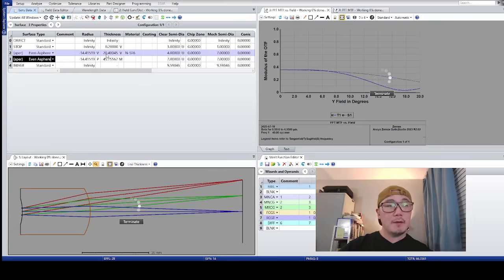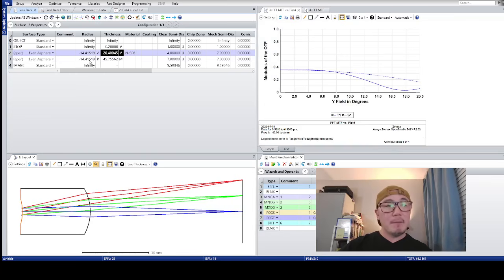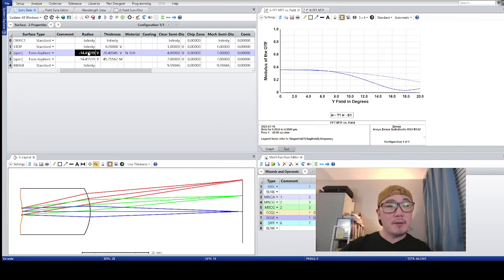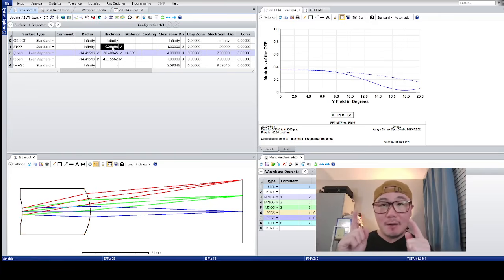Even asphere, and again I'm going to pick up the second radius from the first, make it the same all the time. I'll put a variable on the first radius only. Stop shifting is the magic solution to astigmatism correction. I talk about it in chapter 1 of my book as well.